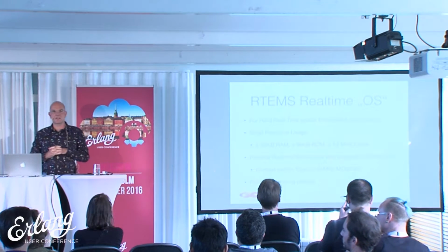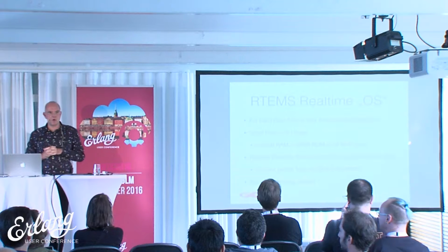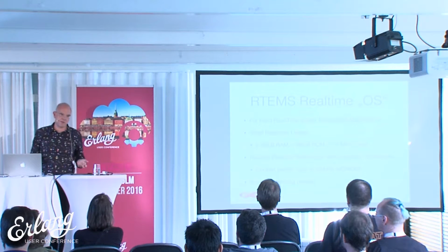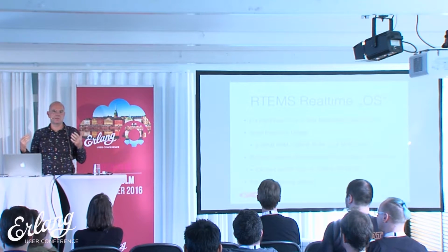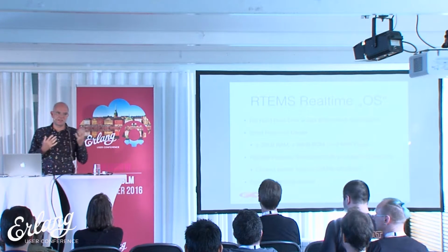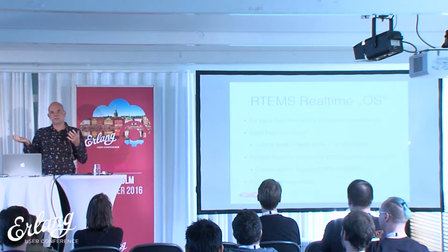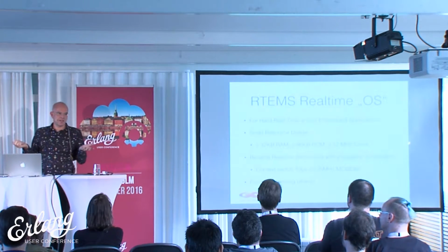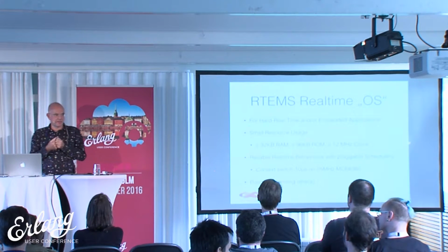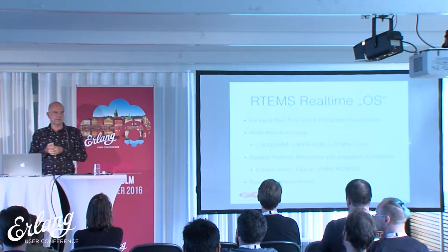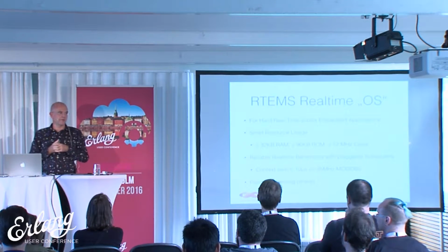RTEMS is a hard real-time OS, but OS with quotes, because it's actually not a normal OS. The E in RTEMS means executive, so it's a real-time executive, which means that you take your application and you link it together with the operating system, and then you basically boot this on hardware, right from reset if you want, or from a bootloader.